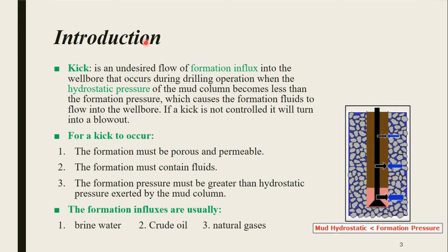Alright, so this is the introduction. In order to get a better understanding of the kick definition, we first have to know the meaning of some specific words and terms. Look at this figure. This is the wellbore, and the area around the wellbore is called the formation, and the fluids inside the formation are called the formation influx, and the fluid inside the wellbore is called the mud. The mud exerts hydrostatic pressure on the walls of the well, and the hydrostatic pressure restrains the formation influx from entering the wellbore.